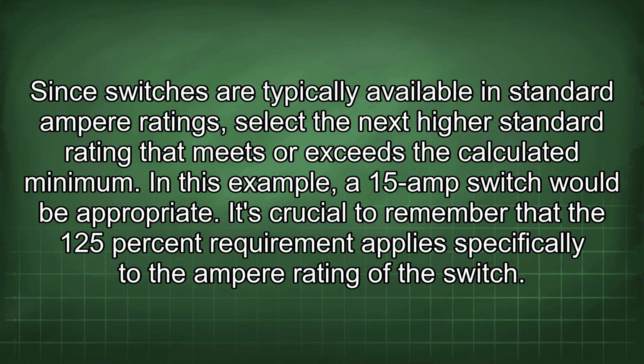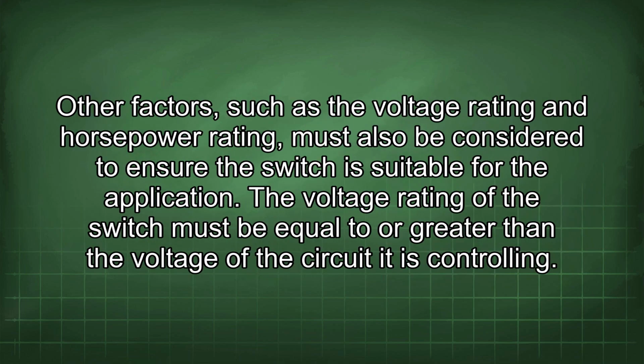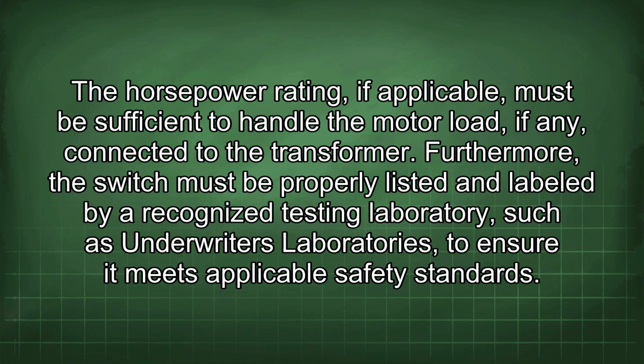It's crucial to remember that the 125% requirement applies specifically to the ampere rating of the switch. Other factors, such as the voltage rating and horsepower rating, must also be considered to ensure the switch is suitable for the application. The voltage rating of the switch must be equal to or greater than the voltage of the circuit it is controlling. The horsepower rating, if applicable, must be sufficient to handle the motor load, if any, connected to the transformer. Furthermore, the switch must be properly listed and labeled by a recognized testing laboratory, such as Underwriters Laboratories, to ensure it meets applicable safety standards.